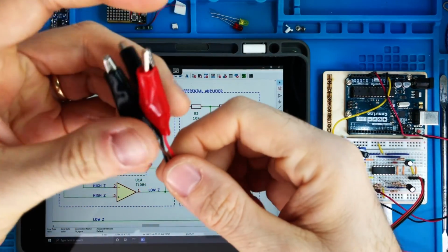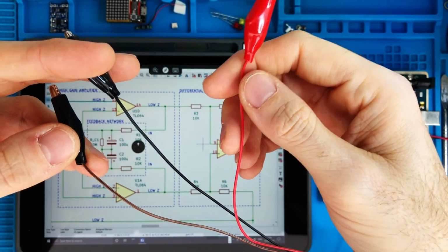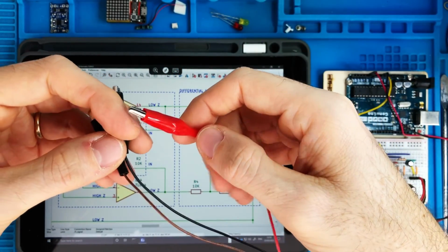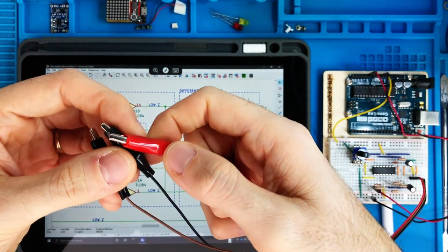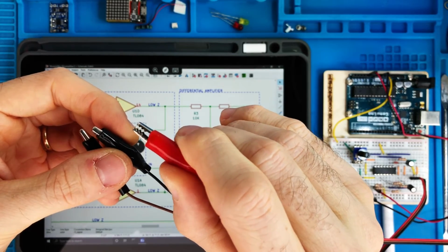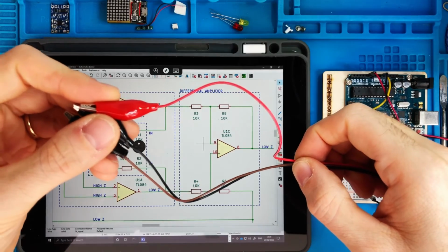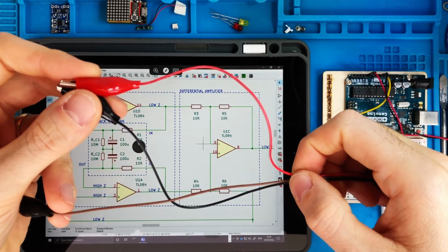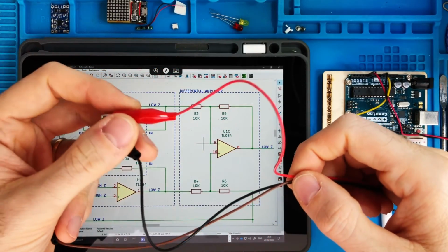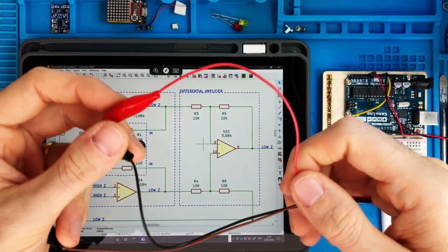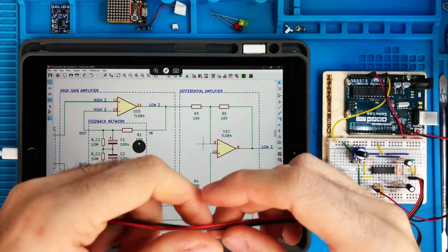So you see they spread apart in different regions of space only where we have them connected to the alligator clamps that then go to the patch electrode. So actually this part is the most sensitive part from the point of view of picking up noise in our system. So most of the noise will be picked up by these loops, intrinsic loops that will be formed by the location of the electrodes.